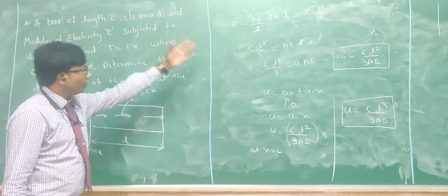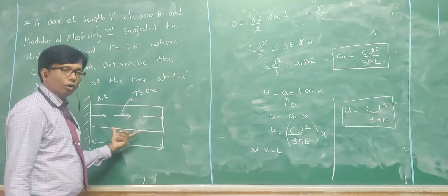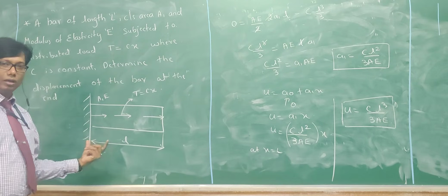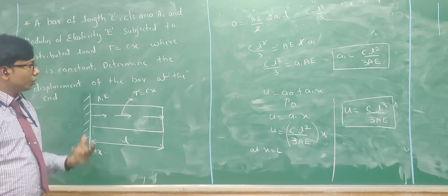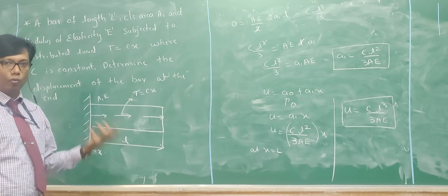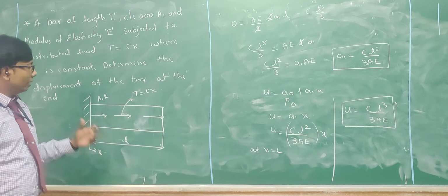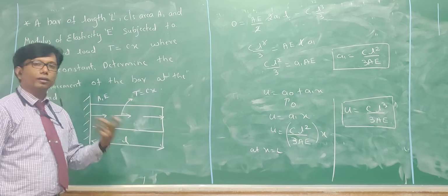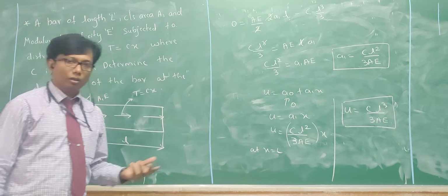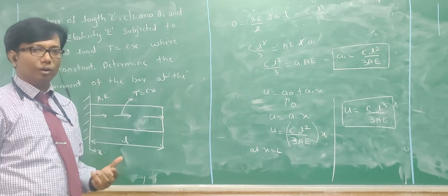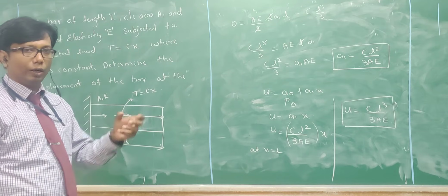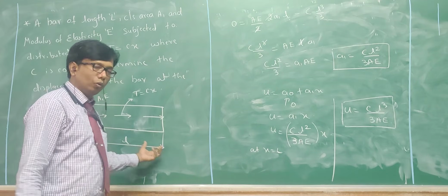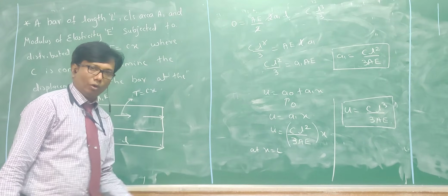So the same formula comes. The only thing is that for the work potential, you have to apply the work potential because of the body force, where volume has to be considered, and that volume has to be converted into area and dx, which you have done for the strain energy of the bar, how you converted V into A into dx. The same thing you have to apply for this. Okay, hope it is clear.